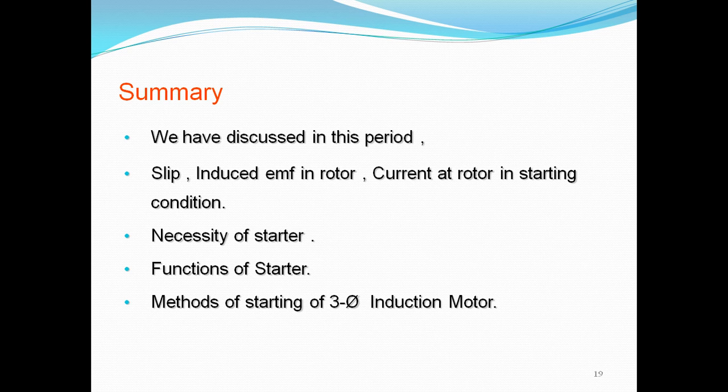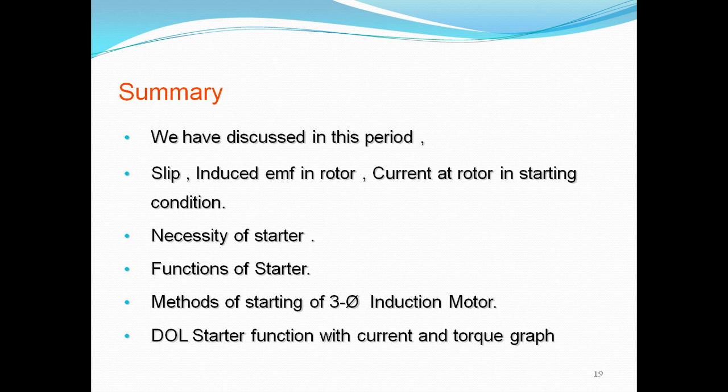Suppose if overload comes, then it draws more current. Because of this more current also, the motor winding is damaged. To avoid this, we have to use the starter. Starter is used only at the time of starting condition. So the starter function with torque and current is explained.